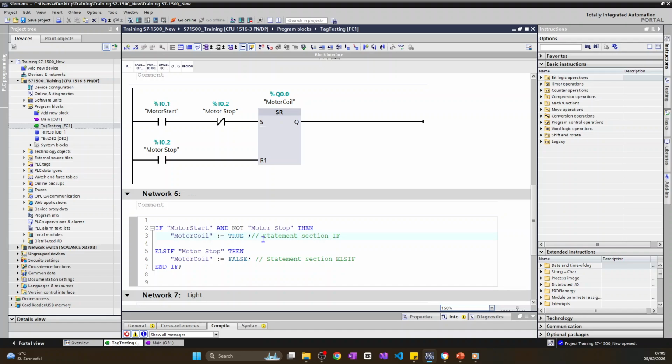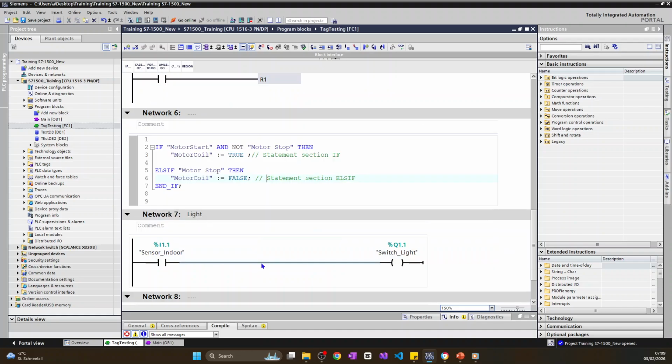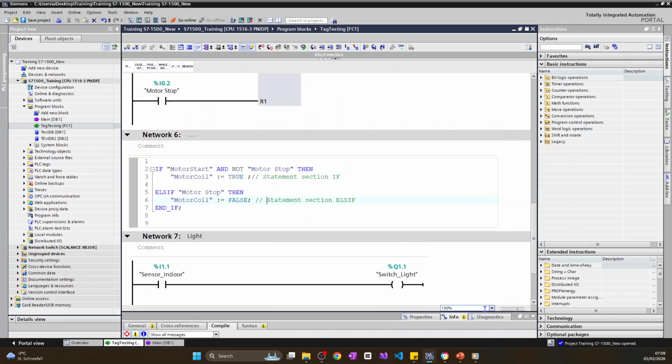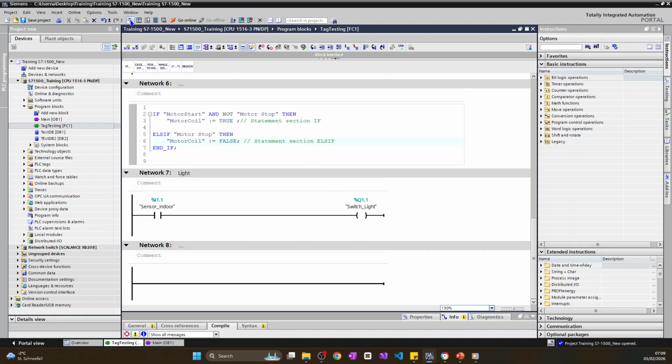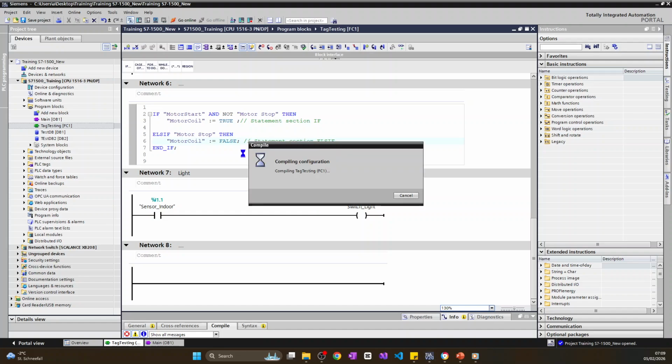Always put notes inside your program. I've advised you earlier so that when someone is reading your code, they understand it clearly. You can always put notes like this. How to do that in SCL is to add a forward double slash. When you add a forward double slash, whatever you put on that line becomes just a comment. We call this a comment. So you need to ensure that you learn how to comment your code properly. What we have now, we don't have errors, we can compile. We have two different programs running on the same network.